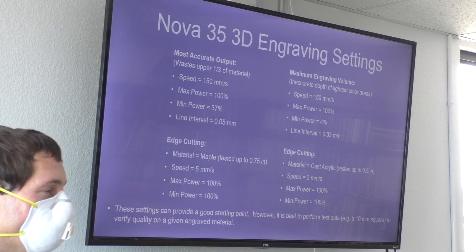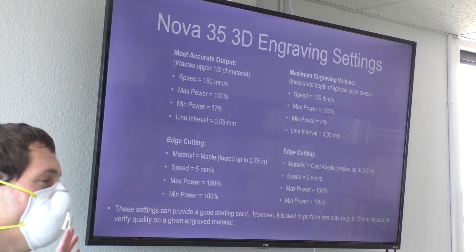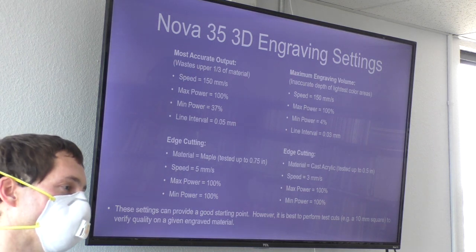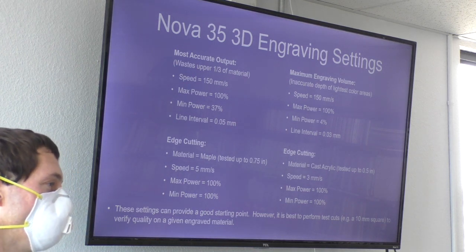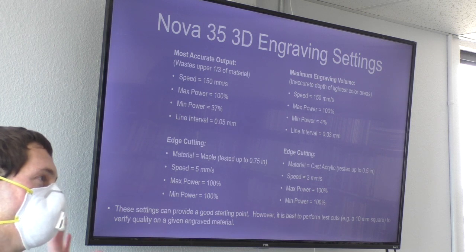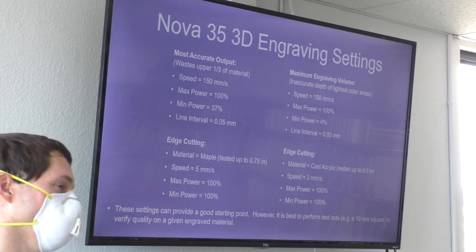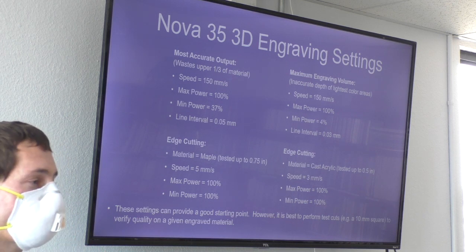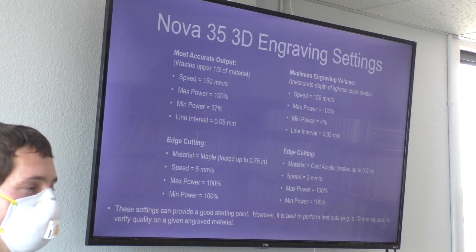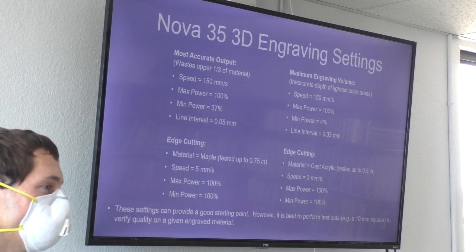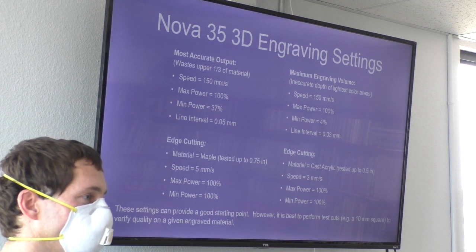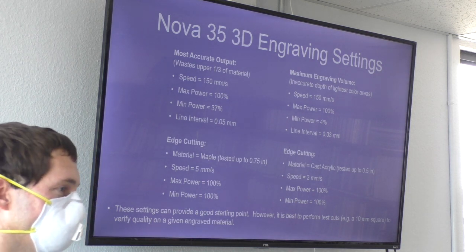Yes, basically there are 2 different percentages. There's the percentage that LightBurn has, and there's a percentage on the controller on the laser itself. So we have set it so that 100% in LightBurn maps to 90% on the laser itself. And the user doesn't think about it. It just works. And it's always going to be a limitation you don't have to think about. Yeah, that was really the crux of my question. Is going to 100% on a regular basis on our machines okay? Yes. The answer is yes.